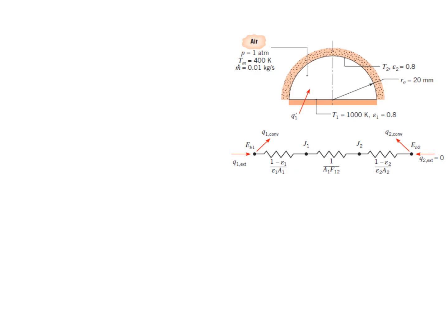Okay, now I have to calculate the external heat from here. In order to calculate that, I need to calculate my temperature on surface 2 as well. In order to calculate temperature on surface 2, I know that it shows up here, the Stefan-Boltzmann constant times T2 to the power 4. So I'll be able to write a relation that has that note in it.